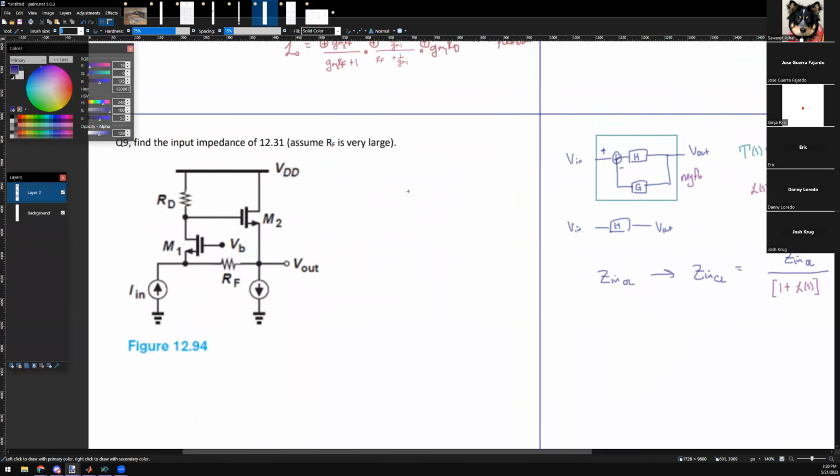In this case where your input was a current source, you assume that the input current source has a Thevenin or a Norton. Therefore, you want the input impedance into the system to be a short circuit so that all the current goes down into the system, not through its own Norton.